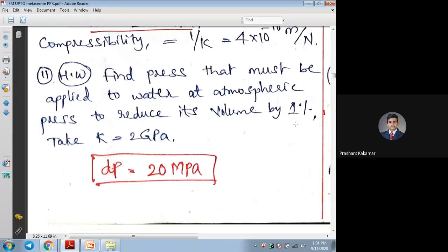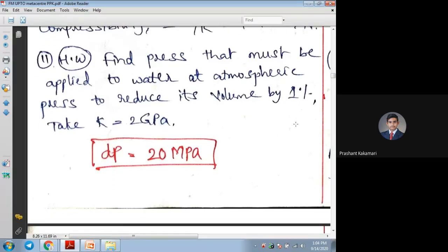Okay. Volume does not change continuously like gases or air. If you take air, just by applying small forces with our fingertips, very small forces, I can compress or expand the air or the gas. But the same thing is not possible for liquids or oil. They have very low compressibility, which requires a very high pressure difference or force difference to overcome a very small amount of change in the volume. That is our understanding here.